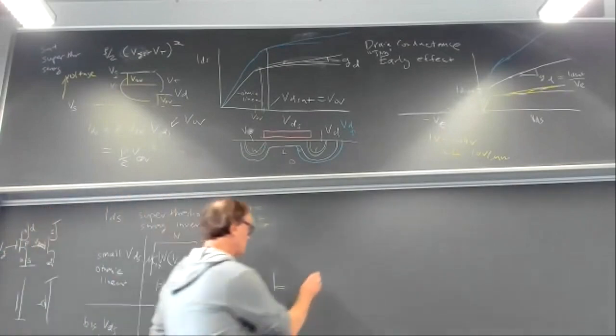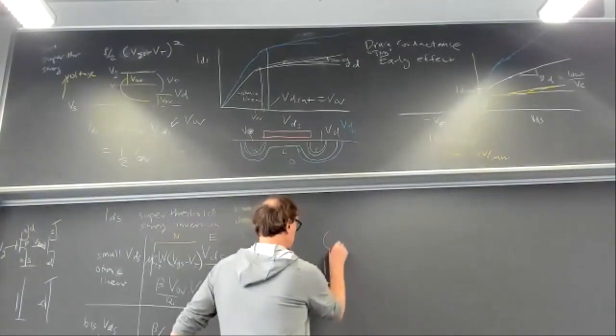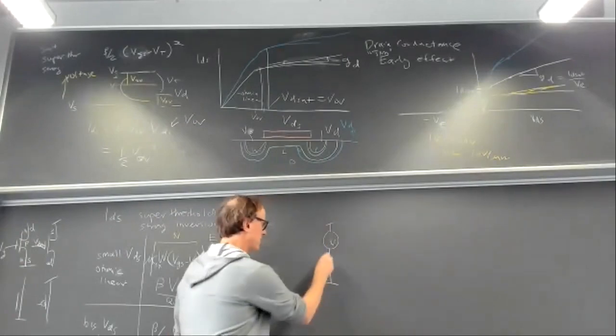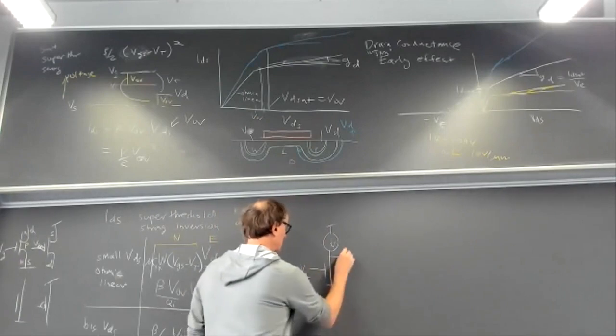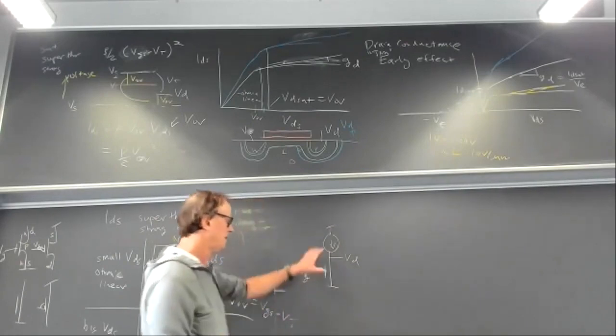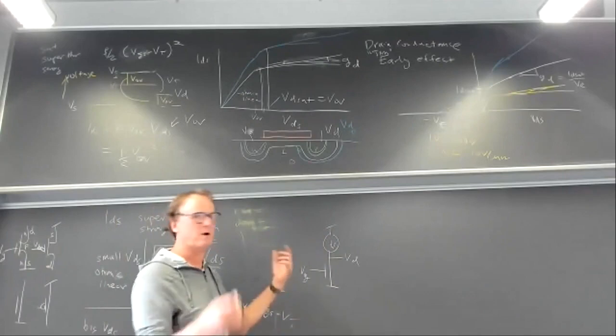Okay, so let's take a simple transistor circuit, going into a perfect current source. This current doesn't change with the voltage here at all. This is the input voltage, and here's the output voltage of this amplifier. This is ground, and this is the positive supply. Now I set up this current source at some level, who knows what, 1 microamp.